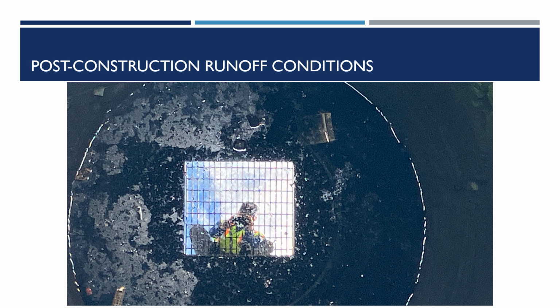Post-construction runoff conditions. It's important to consider additional runoff resulting from new impervious areas. If an increase in off-site runoff is anticipated after incorporating PBMPs into the design, a drainage study must be conducted to assess the capacity of the downstream drainage system. If the downstream drainage system is not sized to handle the additional runoff, redesign of the site or the system may be needed.